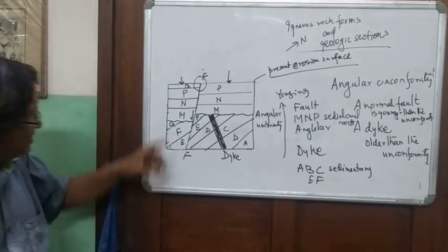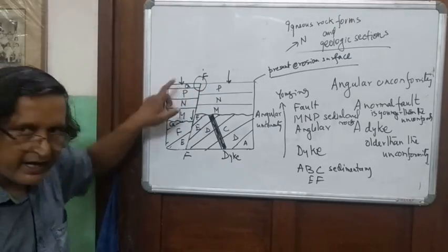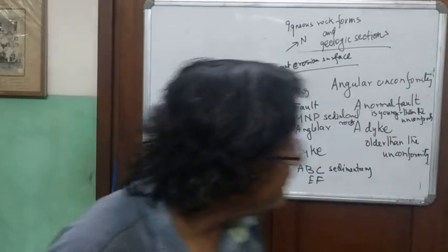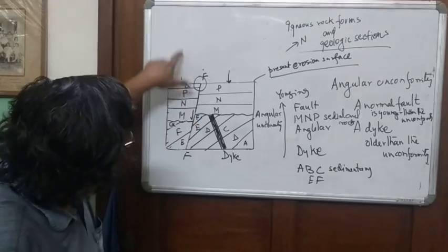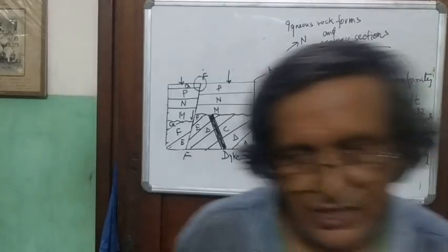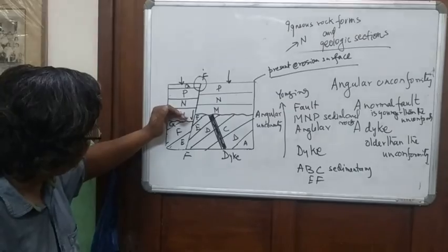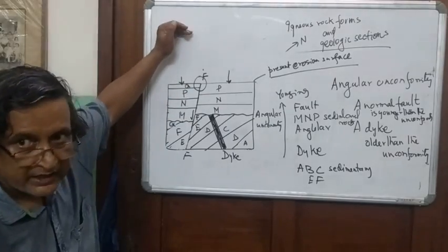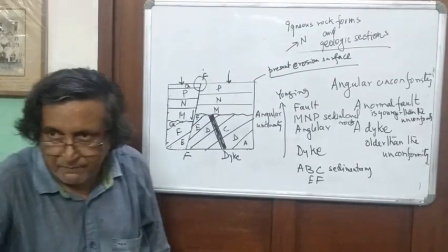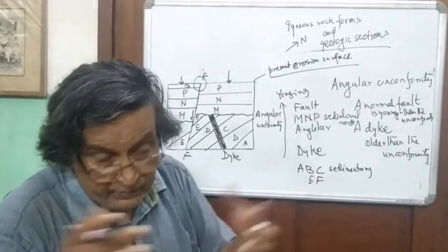So what is happening is, at this point you can record till P. But if you are here, you get an idea that the sedimentation continued for a longer period of time in Q. It may have prolonged even longer. But there is no evidence. There is absolutely no evidence in this geologic section whether the sedimentation of younger beds continued for a longer time till Q, because the whole part is removed. Maybe MNPQ, RS, TXVZ, it all deposited, but the whole thing was removed.